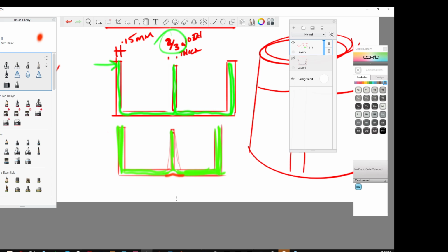It also is dependent on the manufacturing process. So with injection molding, if it's a small part, you can sometimes get away with 1/2 degree. If it's rotational molding, the rule of thumb is nothing less than 1 degree, and that's if you have a completely smooth surface.